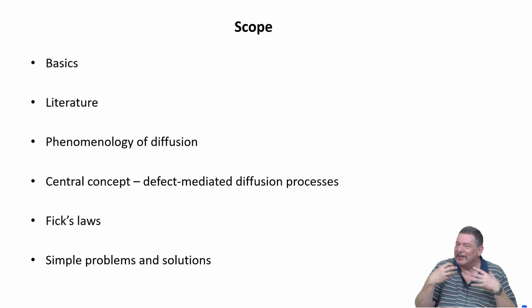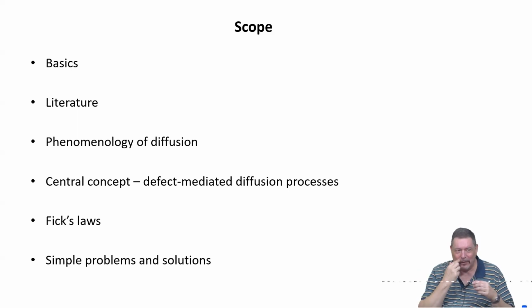Because we normally think of, and I think you also had the mental note of, diffusion occurring because there is a concentration gradient, right? And so diffusion works to minimize the concentration gradient, to homogenize the material. So no concentration gradient, no diffusion. That is correct for a certain type of diffusion, chemical diffusion. But if we just have one single type of atom in a material, we still have what we call Brownian motion. It means atoms are oscillating on their lattice positions.